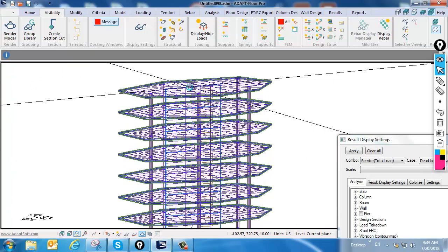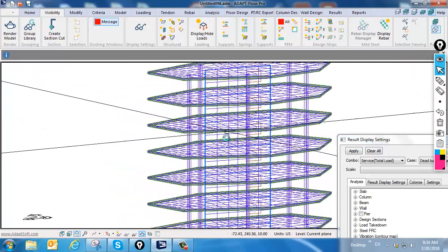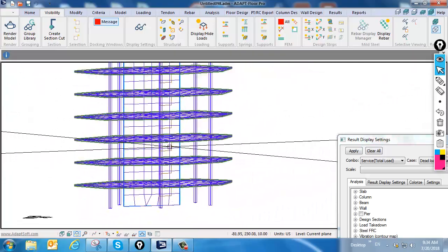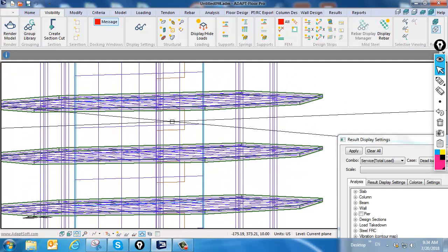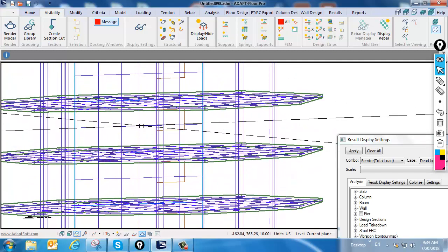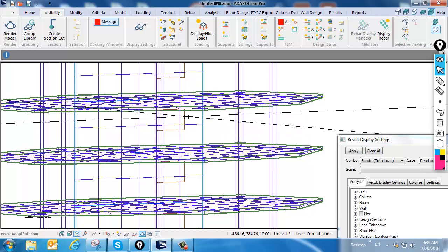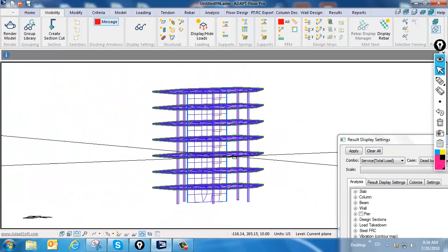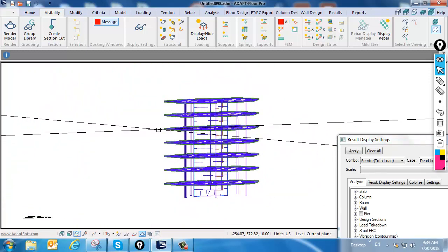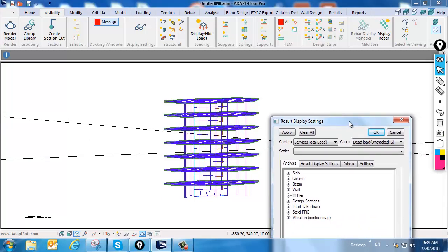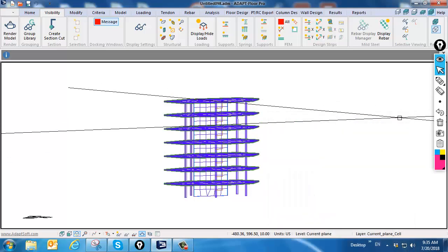This is the old meshing algorithm that's being used for meshing, and you can see that actually the walls ignore the openings. The wall meshing ignores the openings. The mesh just goes right through the opening. It's as if the opening is not there. And that's one option. If you want to take advantage of the advanced options, we have the ability to do that and to have openings considered for wall meshing.